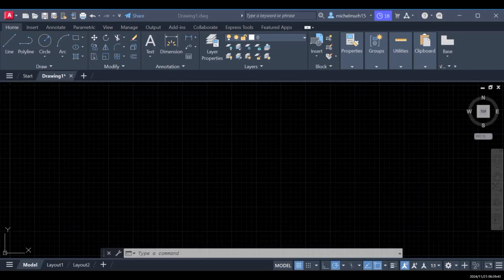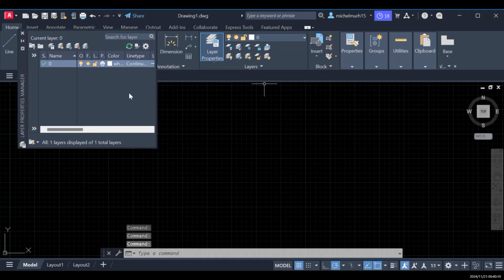So the next step here is to modify and to create some layer properties. But for me, my football field has maybe only 2 different layers. Okay, so what I'm gonna do here, I'm gonna go on layer properties, and I'm gonna define my layer properties. Under Home, we can just go on layer properties, just click on it, and then you can modify. There's a table here, right? So the first layer is the one from the computer. It can be deleted, but it can be modified.